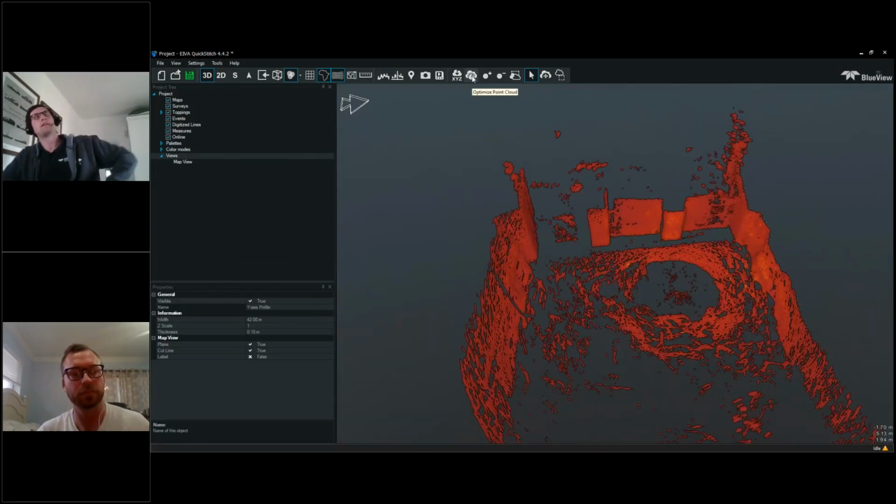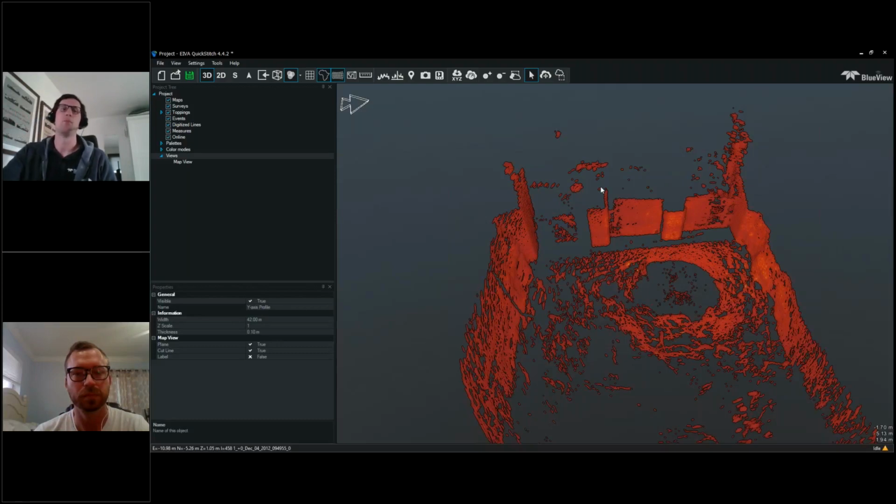Optimization, this can be quite important, especially with denser data clouds. For a system like the BV5000 that's pinging 30, 40 times per second during a 1 degree per second scan, for example, that's a lot of data points. In fact, that's typically more than a lot of users require, and it really can bog down processing. If you don't have as good of a processing computer, which ideally you do, it can really slow down the processing and make it harder for your computer to render.